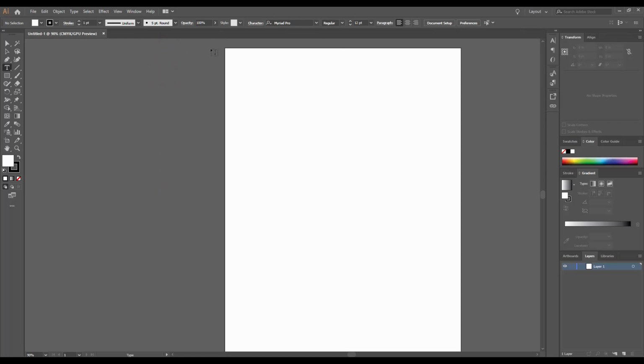So font, and is it going to be bold or regular? Is it going to be 12 point in size? Is it going to be 52 points in size? Is it left justified, center justified? All that kind of thing. And then if I choose a shape, you'll see how that also changes. So the options bar usually changes only when you have a command or a tool active that allows you to change parameters of what's happening.